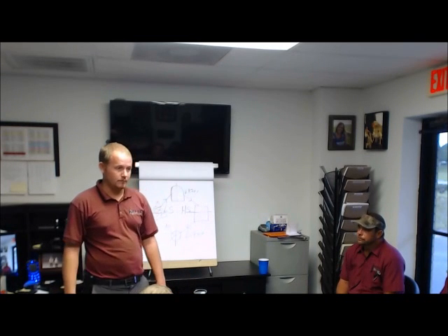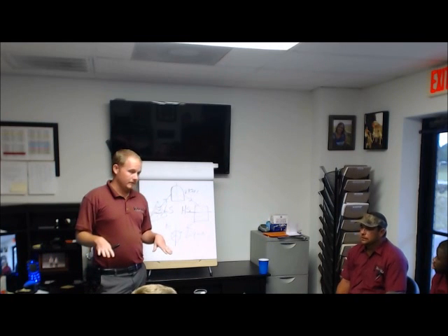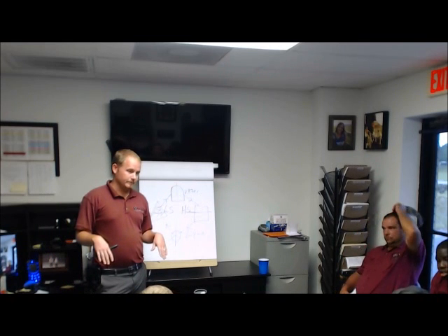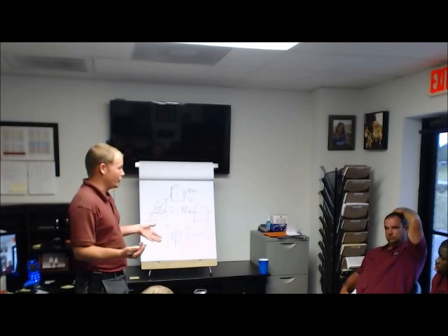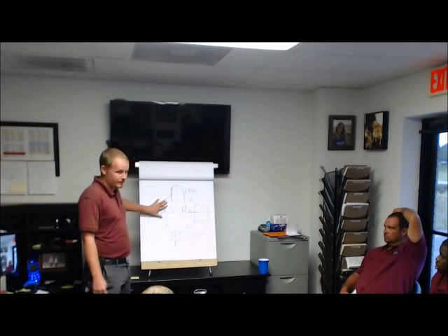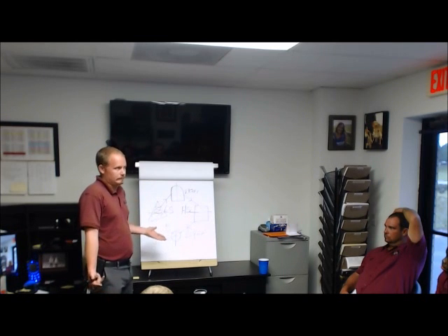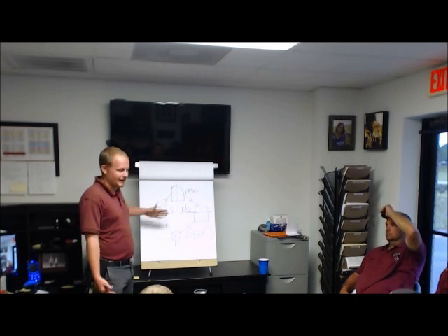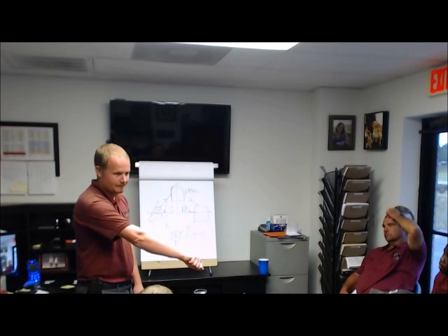Evaporator coil. Drops the pressure. Why is that? Because it's slowing the airflow across it and it's absorbing less heat. Yes, you're exposing this coil to less heat than you would normally have. Okay. Now, why does that affect anything? Well, because now you've got this liquid. It's got to be boiled somehow, right? What you've just done is you've turned down the heat on the stove. So think of it like a stove.